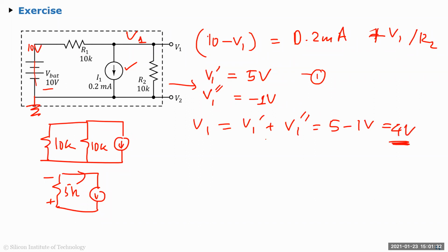Okay, Subham, you agree with this, or you still want to have 0.2 millivolts? Yes, sir. Okay, so don't jump into the answer. See, this is where I say sanity check. You always have to do sanity checks to make sure your answer is right. So when you got 5 volt in one, and you're saying you got 0.2 millivolts in one, that means either your current is in milliamps and resistances are in ohms, or your current is in amps and resistance is in milliohms, right? If either one of them is not right, that means you have made a mistake. So you should go back and check before you say milliamp.